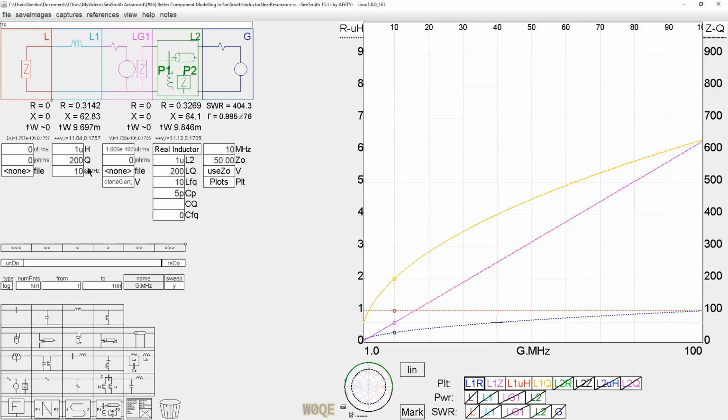As stupid as that may sound, you still see those frequencies used all the time for small inductors. If I wanted to use this at 10 megahertz, but I had the spec at 7.9 megahertz, I'd put 7.9 megahertz in here, and the spec that the manufacturer gave me for the part, and that would be a better model than probably anything else short of measuring it.